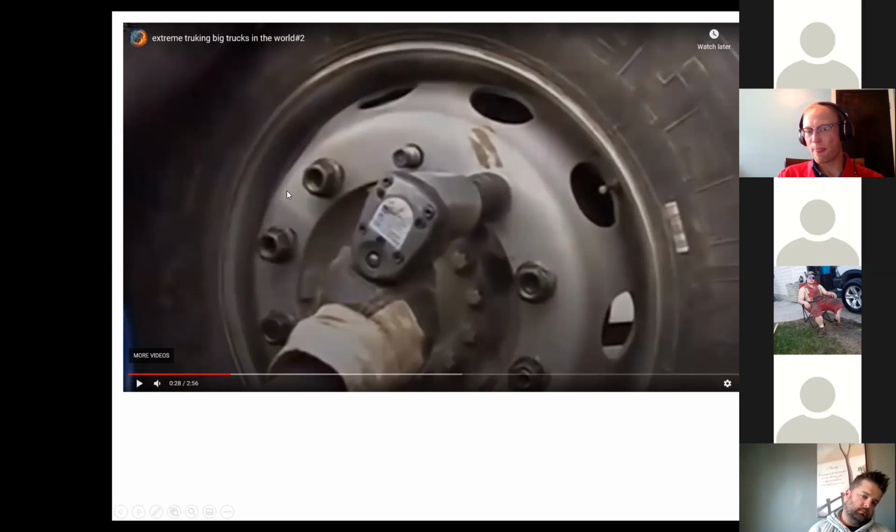But those nuts probably have a collar that goes in between the hole in the wheel and the threads. The threads of the nut will extend significantly below the actual turning washer on that nut. Gotcha, so that might be how they're getting away with it. So it's almost like stud piloted, where the threads are going into this small gap and piloting the hub that way. And so they're getting more engagement than what it actually looks like on the surface here.